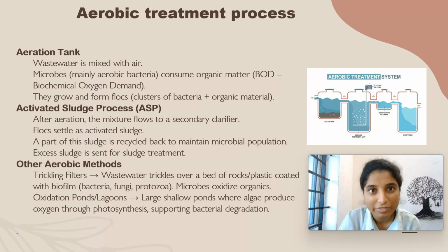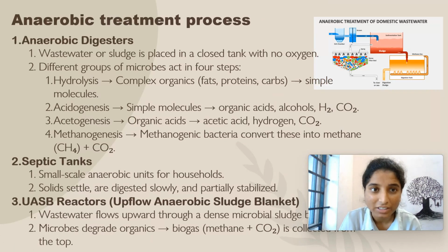Other aerobic methods include trickling filters, where the wastewater trickles over a bed of rocks or plastic coated with biofilm like bacteria, fungi, protozoa. These microbes will oxidize the organic material. Oxidation ponds or lagoons are also used, which are large shallow ponds where algae will produce oxygen through photosynthesis, supporting the bacterial degradation.